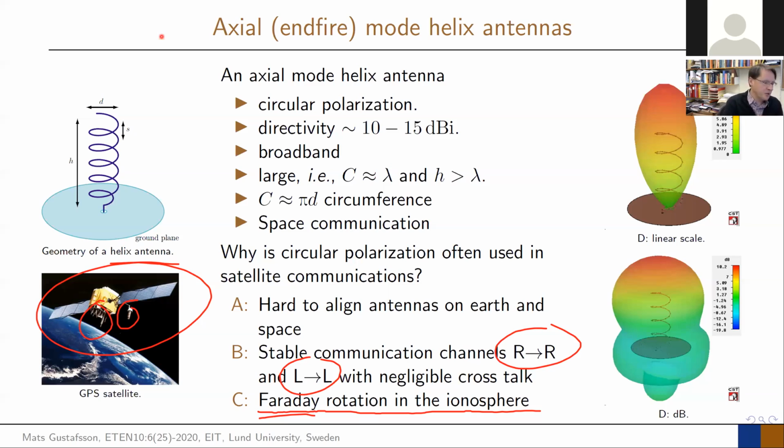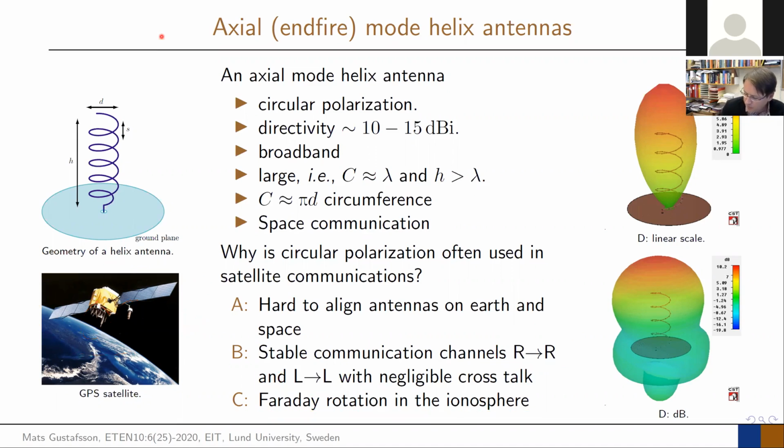There are other uses of circular polarization, and you can have cases where you transmit a circular polarized wave and you have a linearly polarized receiver. It means that it's never perfect, but it's never really bad. Because then you can rotate your linear receiver here, and it doesn't matter how you rotate it. You always receive the same. You lose a little bit of power, but you never lose all of it. So circular polarization is actually a really good thing. And it's used in many, many cases.